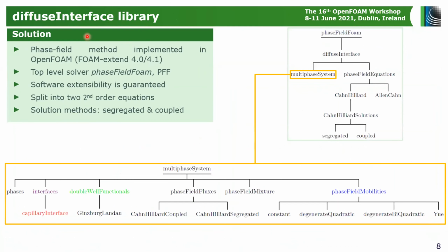Now, this is the diffuse interface library that we developed. The methodology is developed in FOAM Extend 4.0, 4.1. The name of the solver is PhaseFieldFoam. And the way it is implemented is to guarantee extensibility of the methodology. We are splitting the fourth order partial differential equation into 2 second order ones.